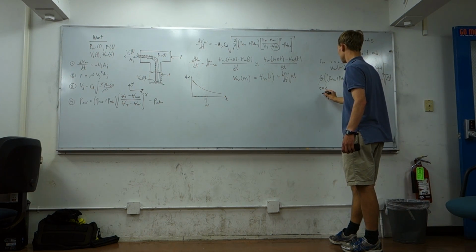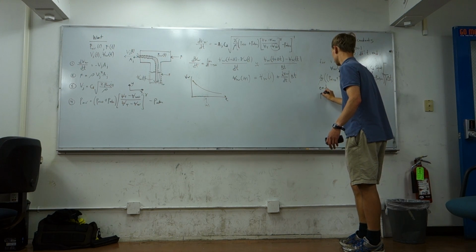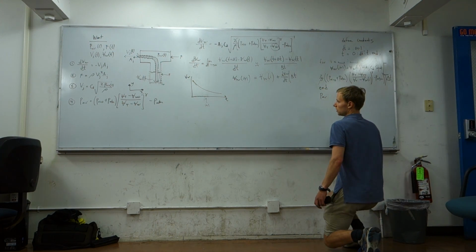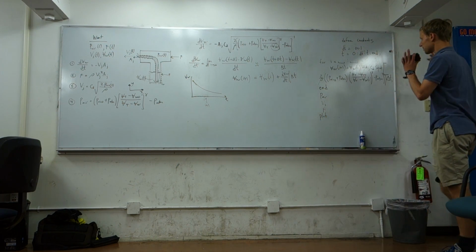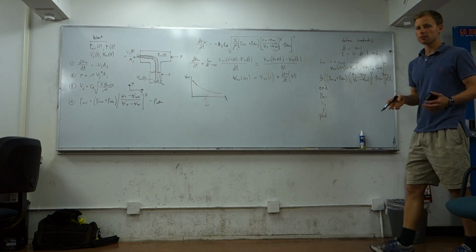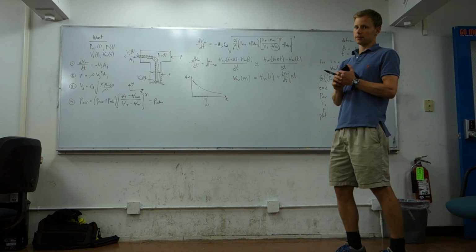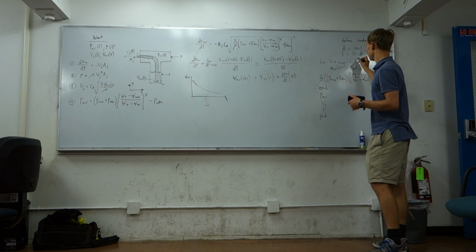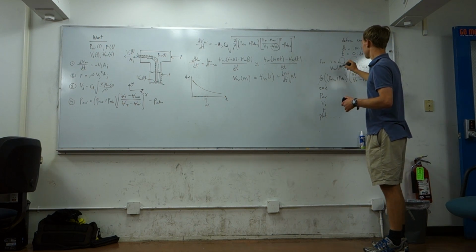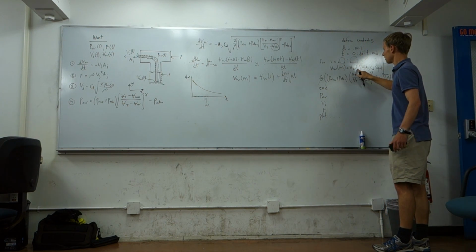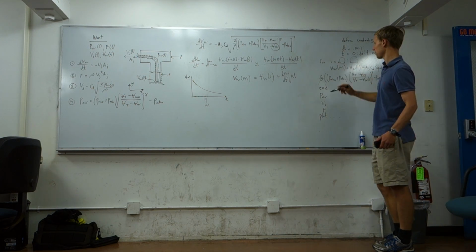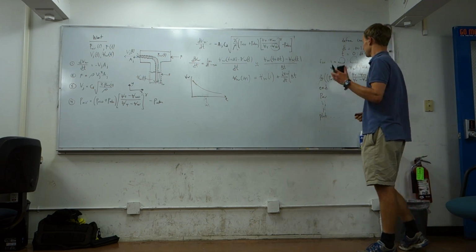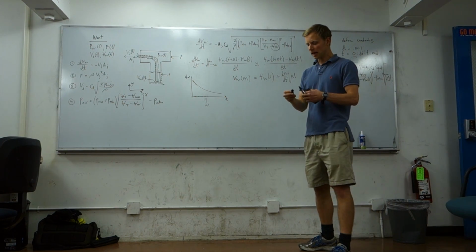And once we have VW, we can solve, like I said, for pressure, VJ, and for force, and then we want to plot. If you write the script up as it is and try to run it, you're going to come up with problems. The errors you're going to have to debug on your own, but some of them will definitely involve the bounds on your for loop. And you're also going to run into problems with the first value of VW at I. We currently have no VW defined, so we'll have to think about that. Okay, that's on you. So let's go now to the result of the Matlab, and then we'll talk more in a second.